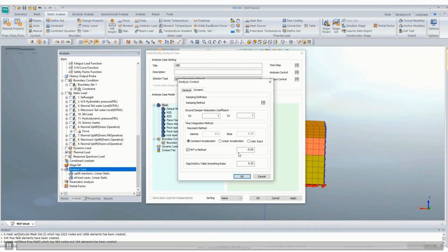Clear. And see this Newmark block again. What I understand is that at some acceleration of, say, ground or different layers of rock, the above layer will start deforming. So that Newmark block analysis is more applicable where we have layers like in a rockfill dam or earthen dam. At some particular ground motion or ground acceleration, that material will start moving.